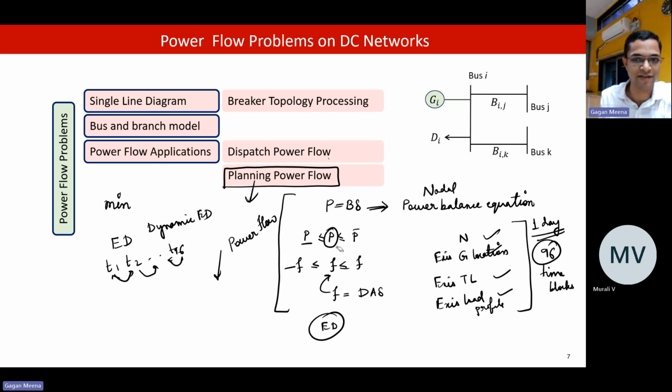We will see this in unit commitment, because we have not seen that right now. But the simplest thing I will just add here. In economic dispatch, we're not talking about unit commitment, but even in the simplest case, one important constraint is that the thermal generator, gas generator, has a ramping capability. That is how much it can increase or decrease its generation in the next 15 minutes. There is a limit on that.